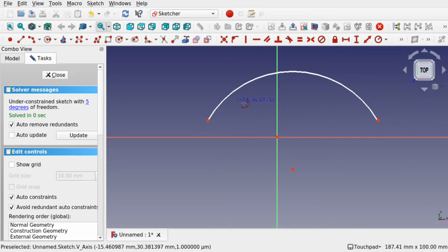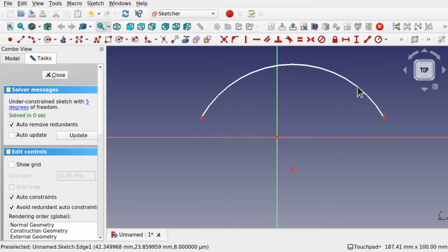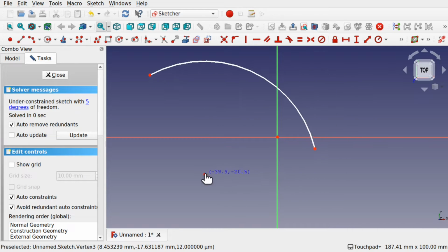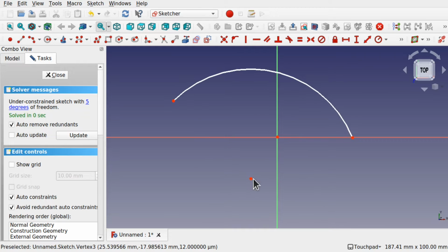There are a number of properties of the arc that need to be calculated or entered first to allow us to fix this length. We can't fix the length on its own because we need a radius and an angle. This is the reason why there isn't a constraint for arc length, because it requires an additional parameter. If you know the arc length, then you have to calculate either the radius using the angle or the angle using the radius. So for that we need to use some kind of formula in there.